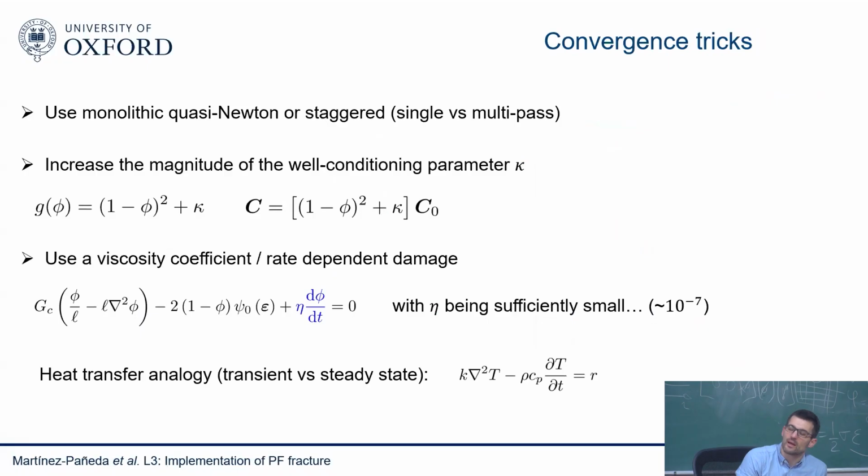So in general, as I said, it's a very robust method. It's by far the most robust I know, so it really works very nicely. However, you may encounter problems where you have convergence issues. It's not unheard of, particularly if you have, for example, yesterday I was discussing with some of you the effect of plasticity and phase field. So phase field converges nicely, but because of plasticity, you are solving an internal Newton-Raphson algorithm to determine whether you're on the yield function or not.